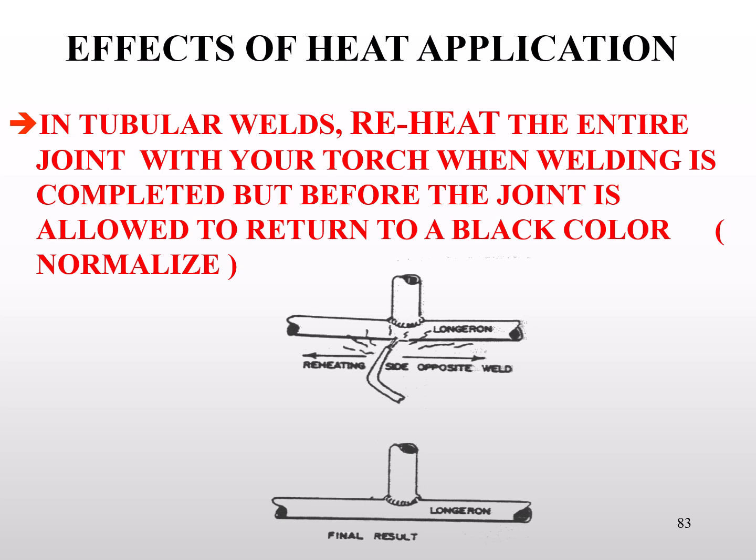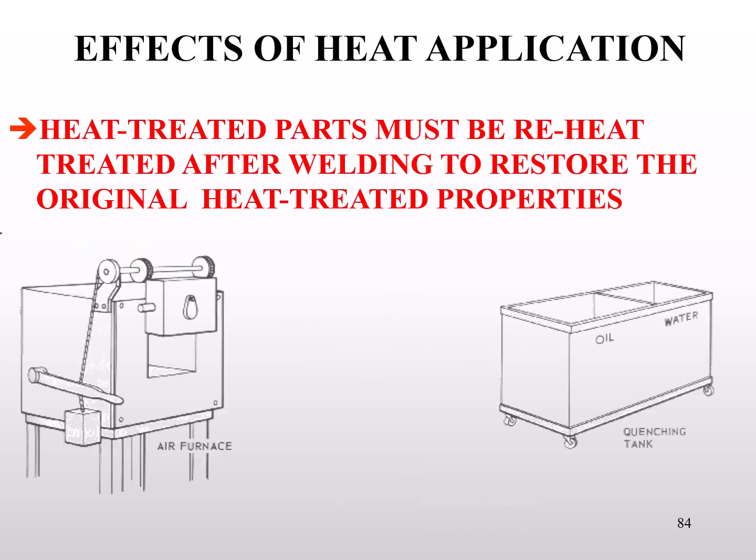Normalizing removes the stress of a weld. Normalizing often can help straighten a part that's warped. If a part had heat treatment applied after the weld is installed on the aircraft, we can't repair it. However, FAA approved welding repair stations can. They'll take that part in, make the weld, then they'll put them back through the heat treatment process. Initially, that's going to normalize the part, then it'll return to the original hardness.